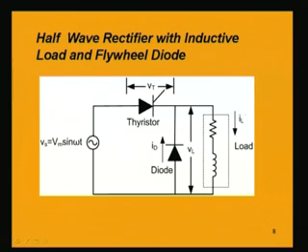Let us consider a circuit. Here, in addition to the thyristor which we were having in the half wave rectifier circuit, we are also having a diode. This is a normal or ordinary diode connected in the circuit. So, basically what does this diode do? Now, let us try to understand the behavior of the circuit. We are having an inductive load as it is, a resistance and an inductance in series is the load. The current through this circuit is IL, say, voltage across this load is VL.